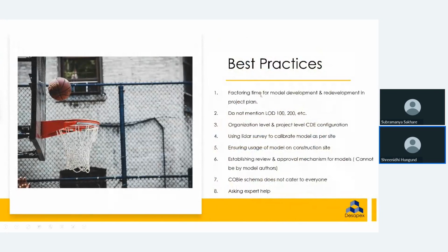So what are the best practices? Factor in time for model development, whether it is done by consultants, architects or contractors. Please factor in that time for model development and redevelopment whenever there is an RFI or a design change or anything. And don't mention LODs. That is what we tell.